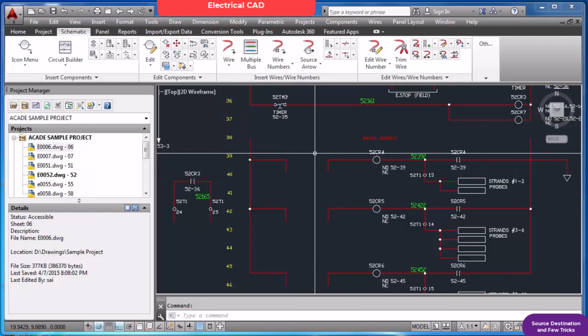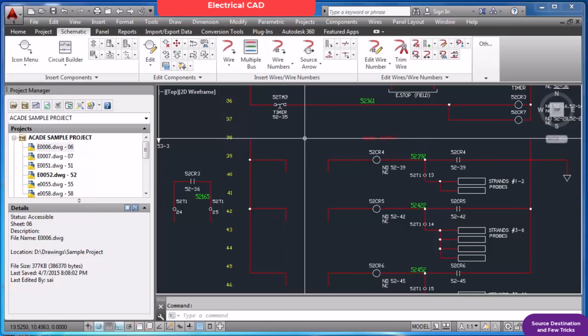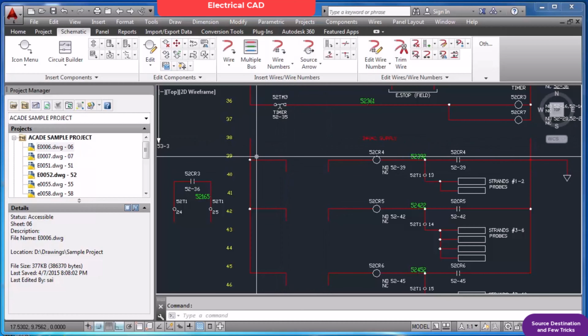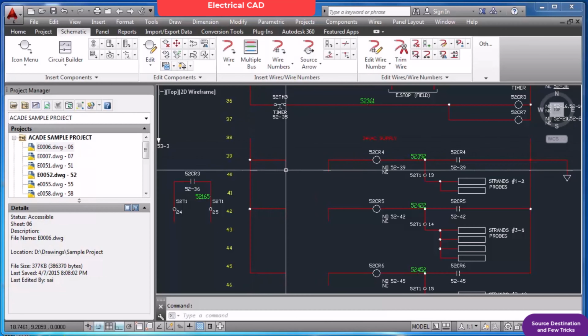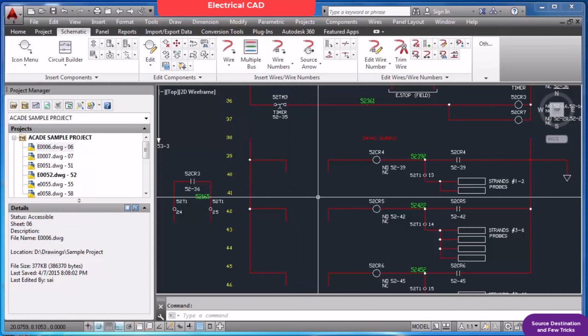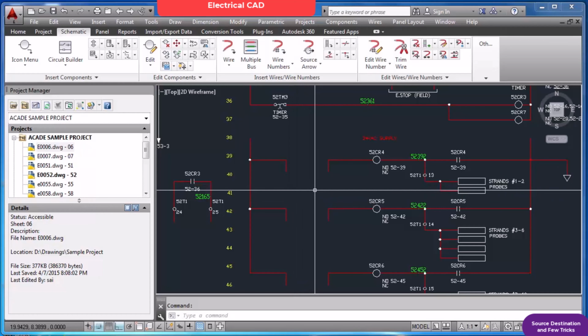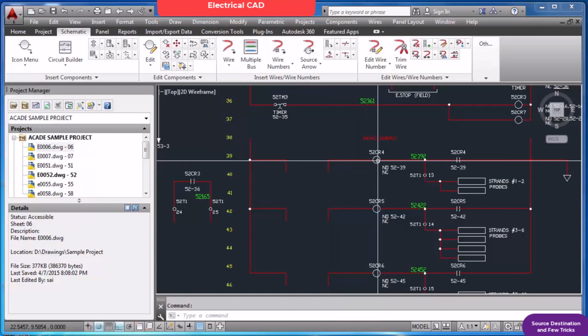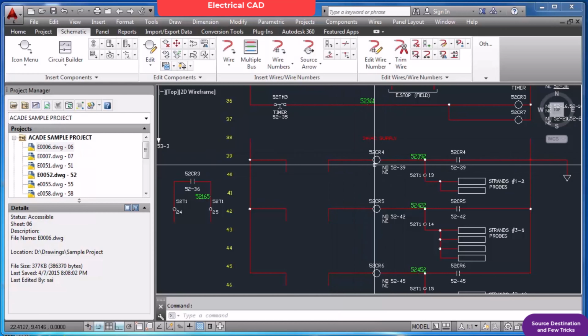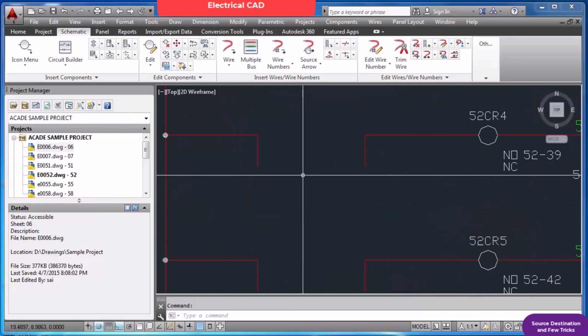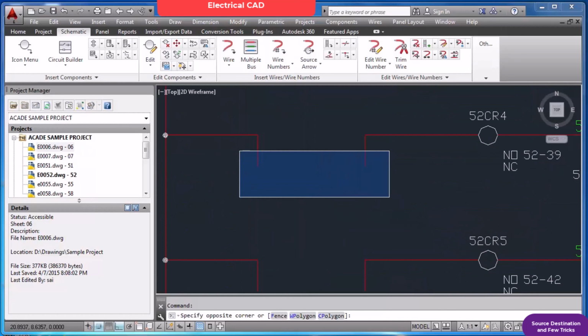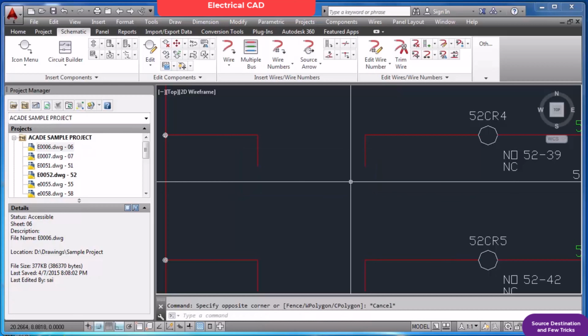What it does mean is, when we provide a 24 volt AC supply, the phase will come here, and from here it will go to one relay board, and from there it will come here and pick up this control relay. That is basically the circuit. And what I mean to say again, we have to put a relay in between. That is not in this sheet. The relay we are going to show in another separate sheet.